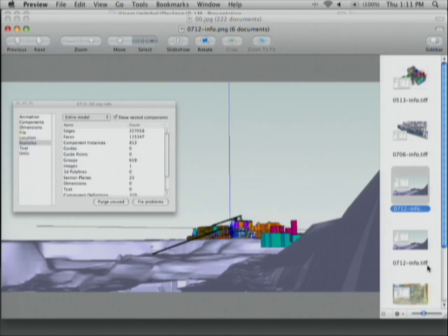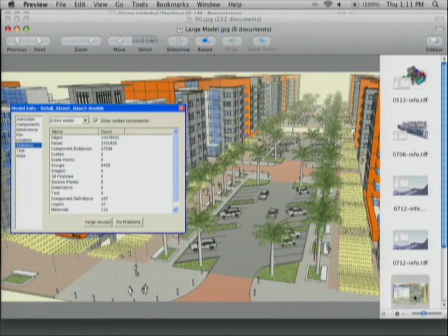This model is a little smaller, 100,000 faces. I work really hard at trying to keep the faces small by not using circles with 24 sides unless I really need to. I often send my employees back to the drawing board when they bring me models that are too large. This is a model done by Daniel Toll. I don't know if I can read that number. What is it, 10 million edges and 3 million surface faces? I think this file is only 16 megs, or it's relatively small. I think the vegetation gives an incredible number of surfaces, but the file size is not that large.